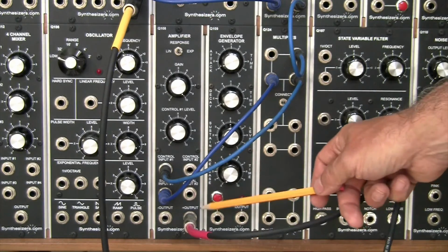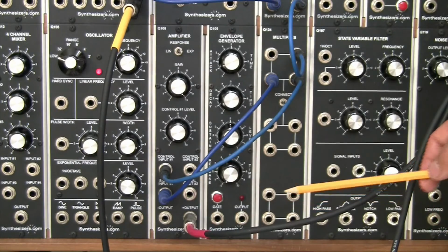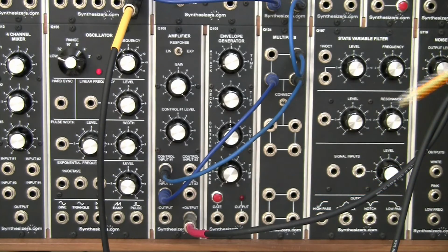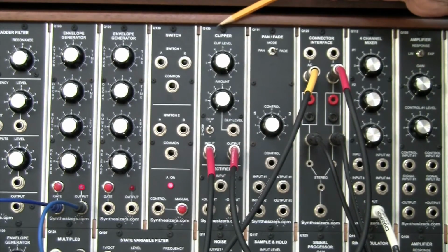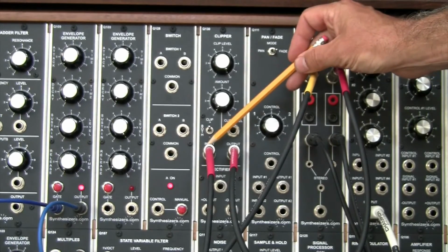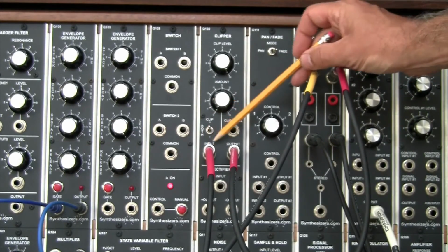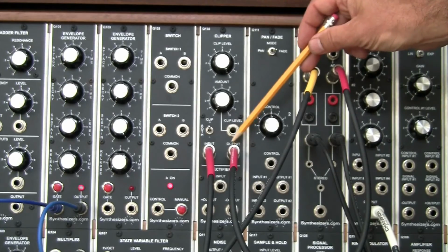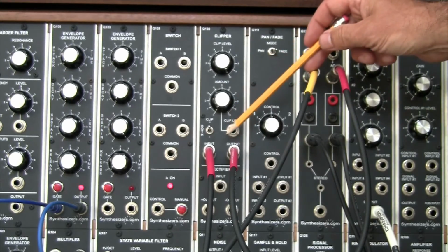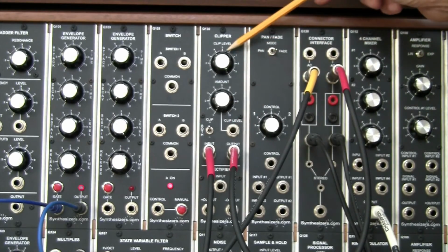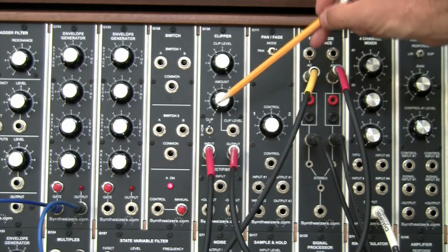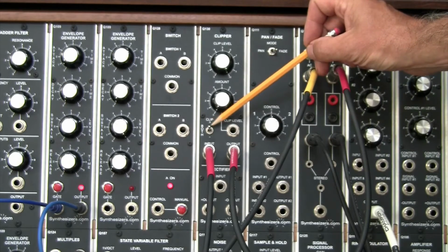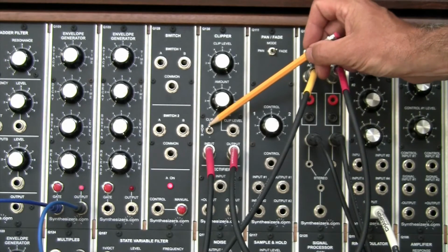The output of the Q108 here comes back up to the input of the Q130 Clipper rectifier, which I'll show by moving the camera. Okay, the Q130 Clipper rectifier is here. Its input is coming from the output of the Q108 right into here, and its output is going off to the scope so that we can see the waveform. Initially, we want to set the clip level up here at 10. This amount knob doesn't do anything. I have it at 0, and the clip polarity is set to positive.